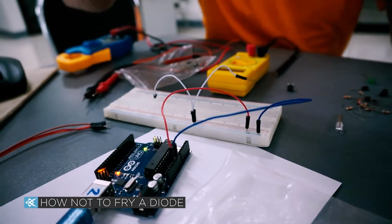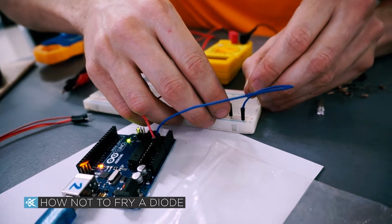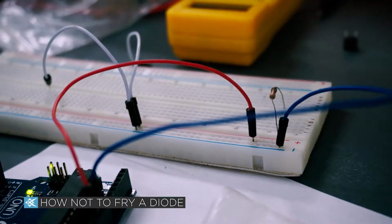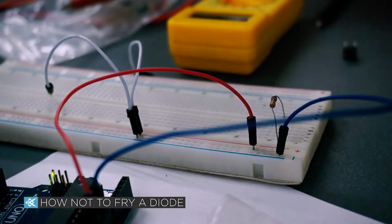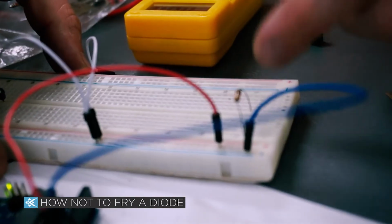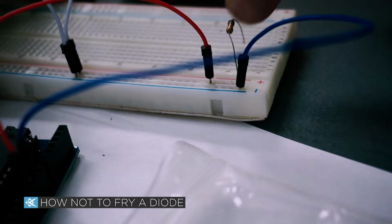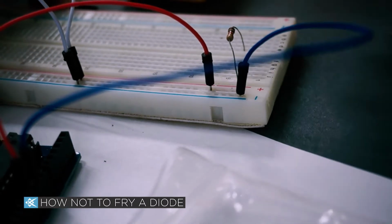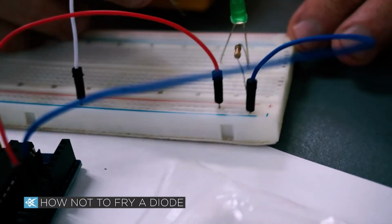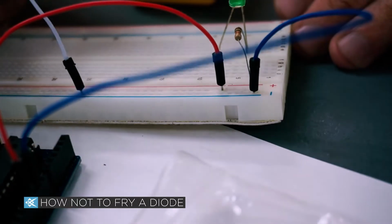There's this 1K resistor, and we're going to jump it between the plus and somewhere, let's say here. Which one did we say was the positive? The long one, right. So now I put the positive there because that's 5 volts. For the moment, there's no current. Since there's no current flowing through the resistor, the voltage across the resistor is 0. Then I connect back to it, and when I connect the ground, I'm going to close the circuit and it should light up. And it doesn't, so something is wrong.